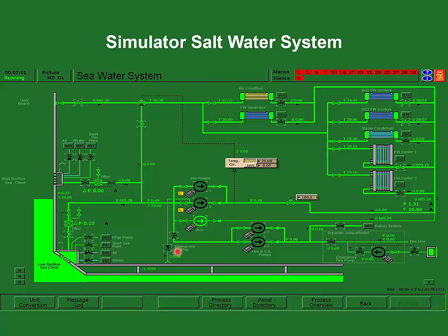Now, just understanding with this, that if you were to do this, in other words, you would make sure that all your water is going overboard. You would open the emergency bilge suction and close your sea suction and use one of these big main pumps to pump bilge water. You are going to pump any oil in the bilges directly over the side. So this would never be used unless it was an emergency.